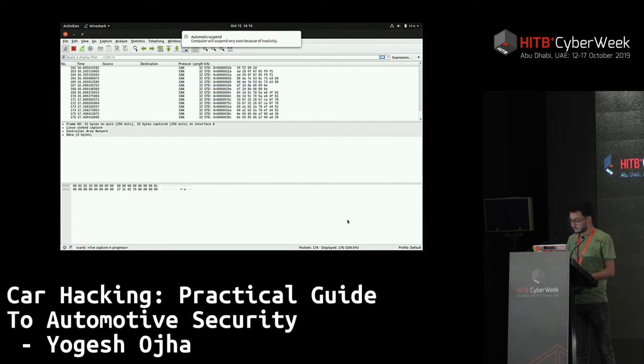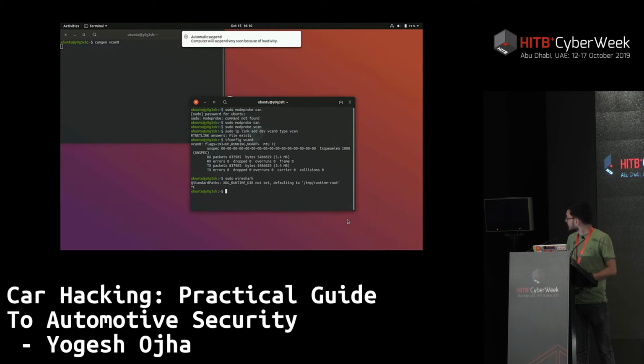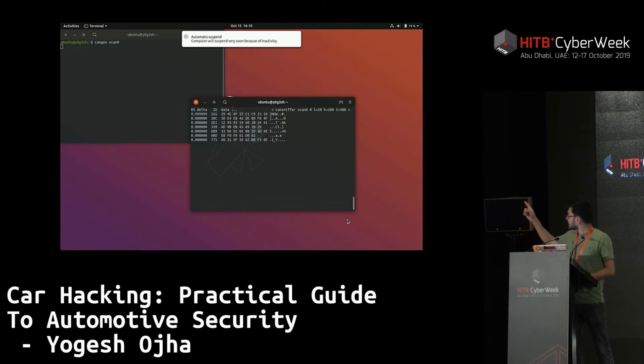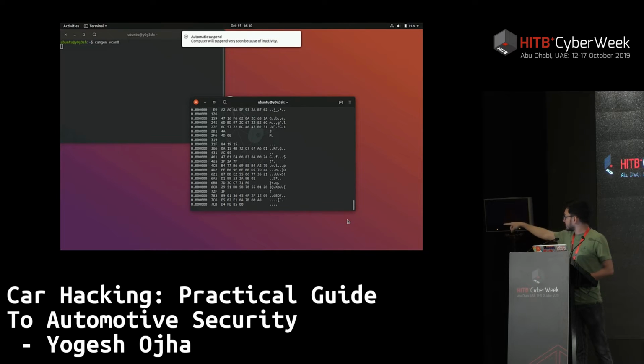You can use whatever tool you feel like. But that can also be done using candump. We'll use candump later. We'll use cansniffer, cansniffer can0. So you can see whatever CAN messages are being generated by cangen are actually displayed here. If you see the same screenshot that I showed you earlier, with the arbitration ID and then the message, it is being shown here.